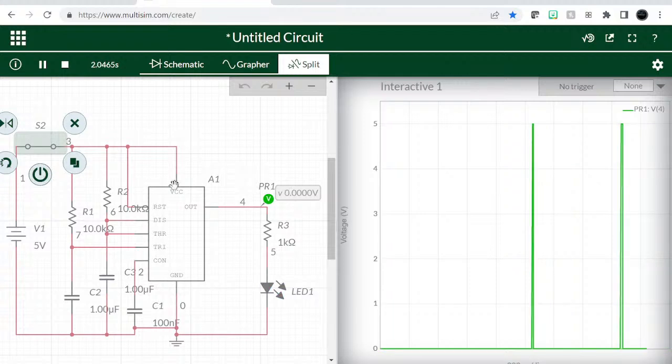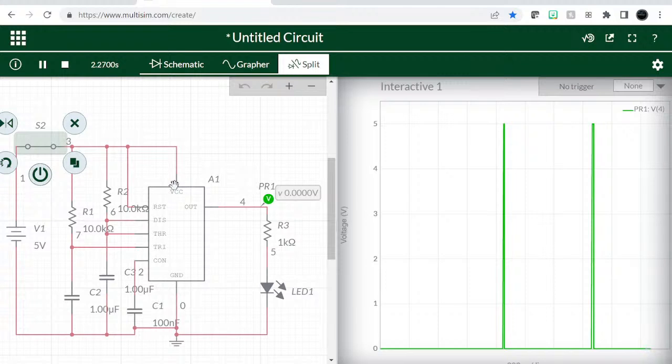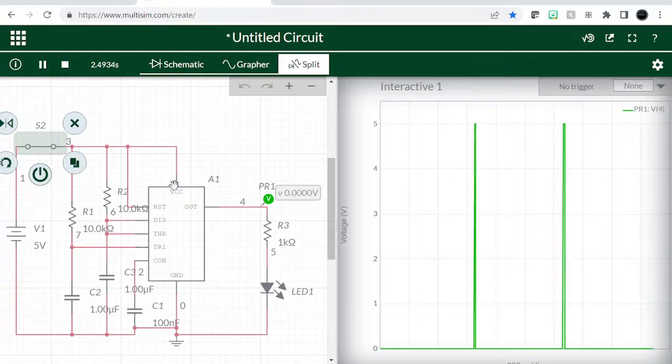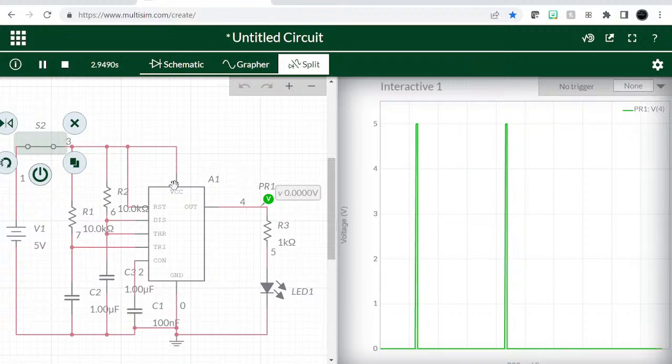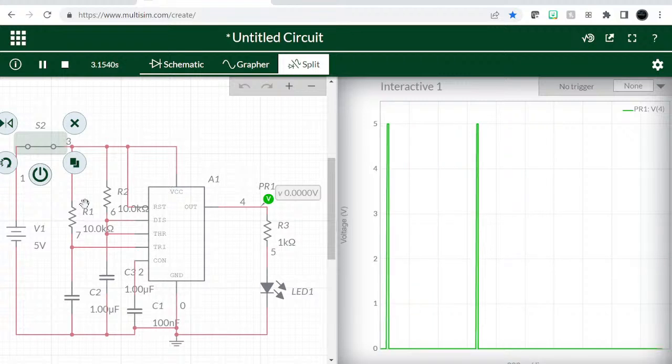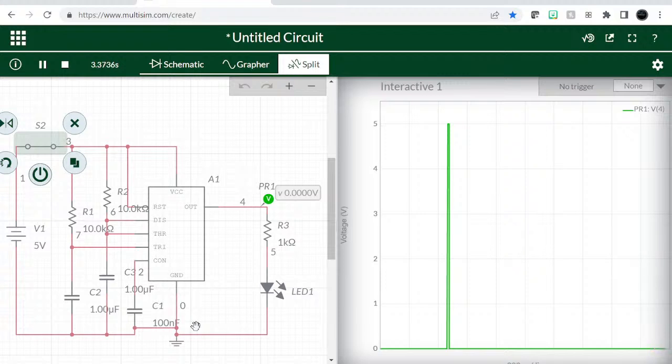All right. So you use this to reset a system, especially if you build a circuit that has memory and some storage that you need to reset. You need to have everything start at 0 or start at a particular point. You want to have a monostable timer somewhere that will give you a power up one shot to reset all your system. The moment power is inserted into the system, it will reset. You can use a microcontroller to do this. Actually, you can use other things, but if you don't want to program anything, you just want to do hardwired, this is an option for you.